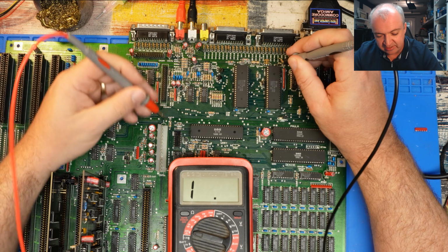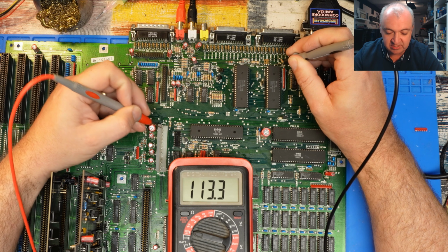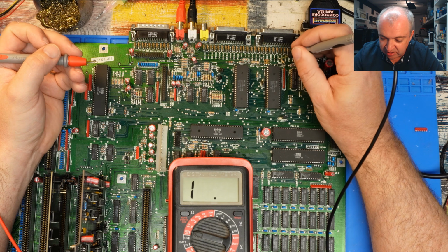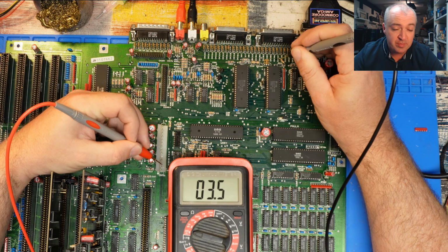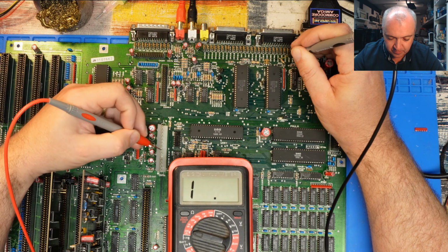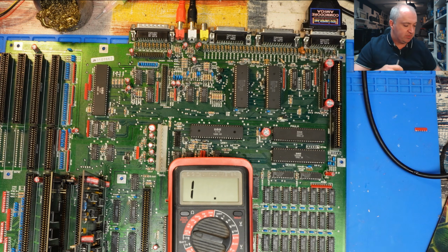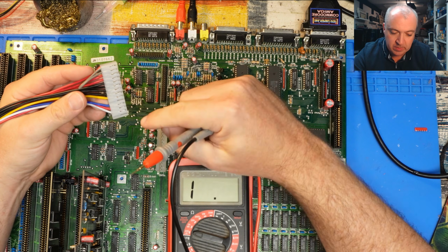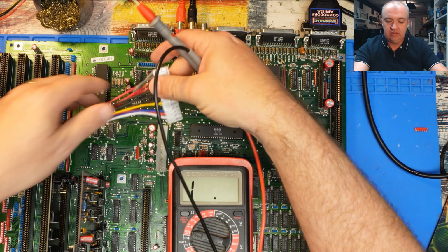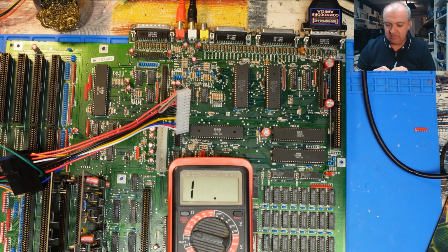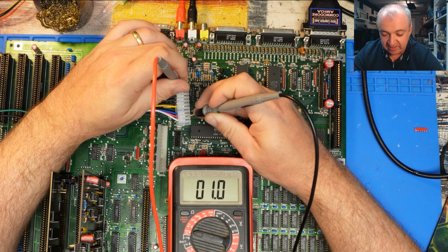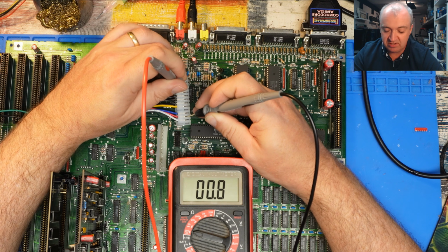So it was originally connected to 5 volt. That's those 4 pins at the top of the power connector here. But that trace that we have connected it to now, well, it goes to that 3rd pin up on the power connector and nothing else. But if we take a look at our adapter cable here, well, that is also red. That is also a 5 volt. Now, because we're using this adapter and inside my ATX PSU, those are connected. So this is going to make no difference whatsoever.